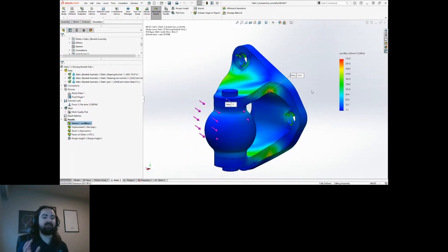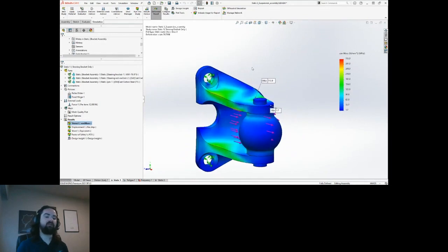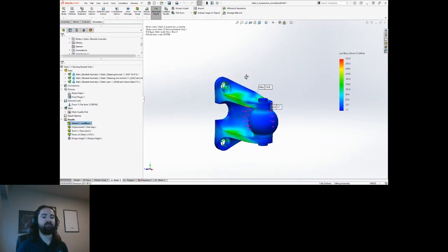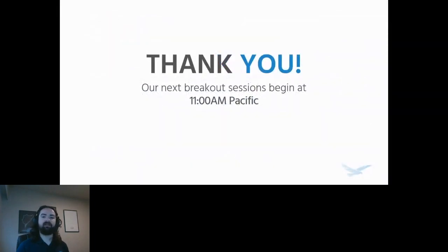However, either way, if the design insight plot is used to decide which material to remove and which material to leave behind, you can be confident that if the model is weakened at all, it will be by a very minor amount. And of course, when modifying the model in any way, you wouldn't just rerun the one static study. You would definitely want to rerun all of the studies you've created for that model so that you can get your updated results, even if it's only a minuscule change. Now, I don't want to waste everyone's time with that, so I'm just going to run the static study that I already did. All right, and so with that, that's actually all I have for you in this session here.